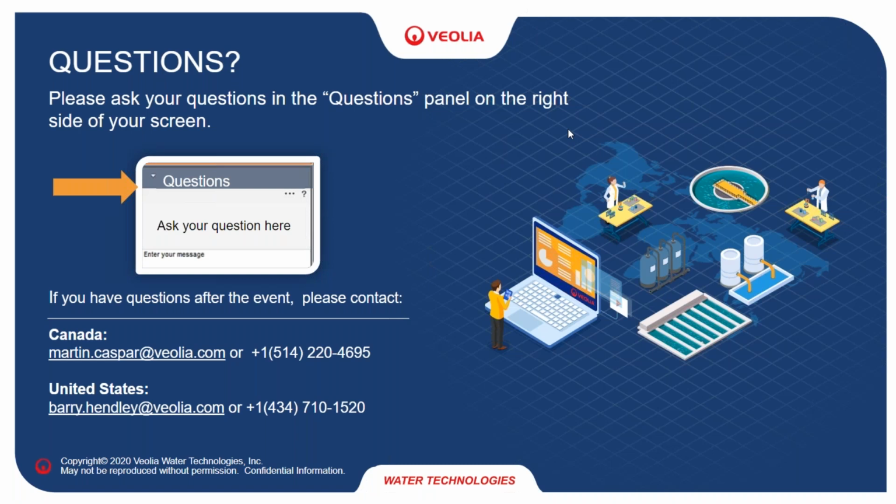Okay, Actiflo is optimized NTU wise. Our filter life is a continuous issue. Where should we start? I would start with polymer, optimizing polymer. See if there's something you could do there, but seeing what is carrying over. Is it creating mud balls, is that why the filter life is running short? Or is it something that's in the raw water that's causing the filter life issue? Or are you carrying over sand? It wouldn't really affect the filter life, but what is the sand carrying with it?